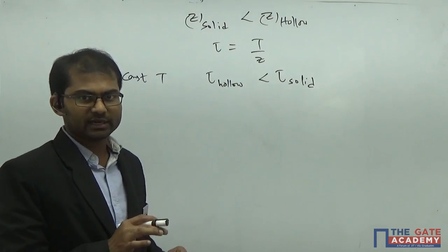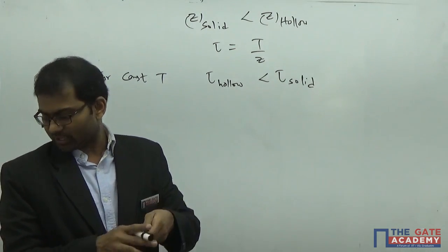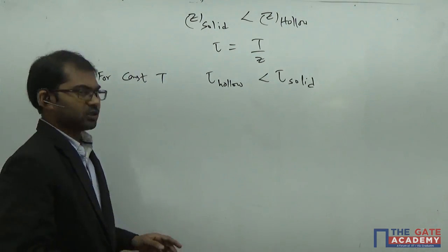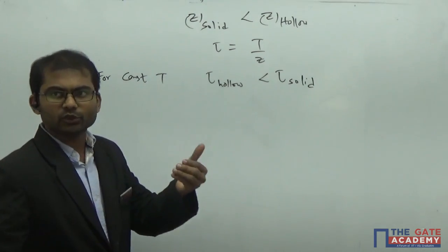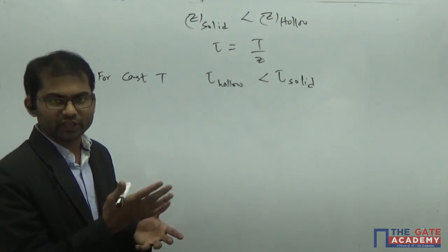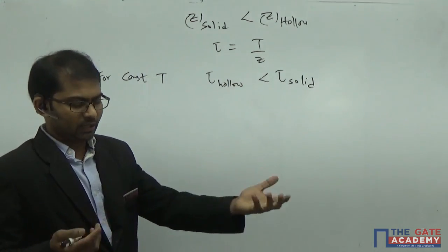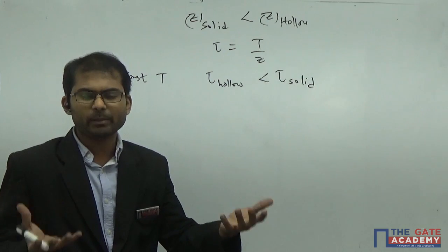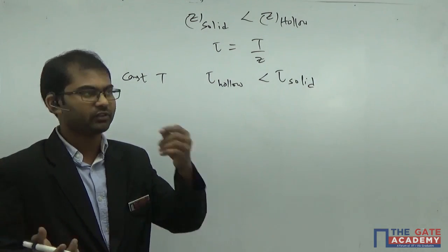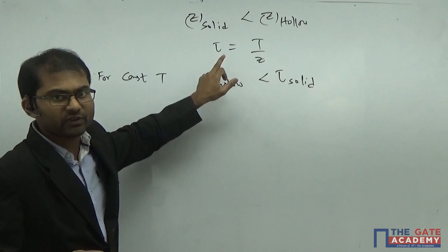So basically we understand that if you do the experiment at room temperature, we'll come to know at what value of stress it's going to fail. So this maximum value of tau max is actually fixed here. Anyhow, in this case, you are comparing two same materials, a hollow shaft and a solid shaft, so this thing is constant. The maximum value is constant here.